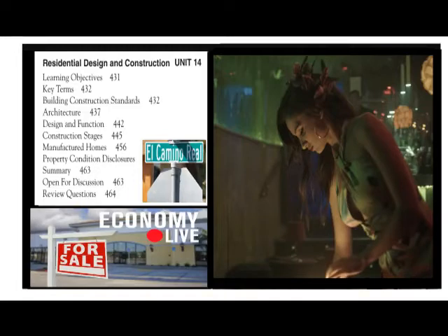Radon is a gas that occurs naturally in all parts of the country as a result of the breakdown of uranium in the soil. It is harmless when it dissipates into the atmosphere, but in the enclosed environment of a crawl space or basement, radon can accumulate to high enough levels to increase the risk of lung cancer and other ailments for residents.